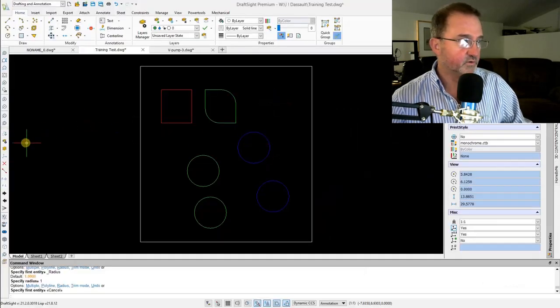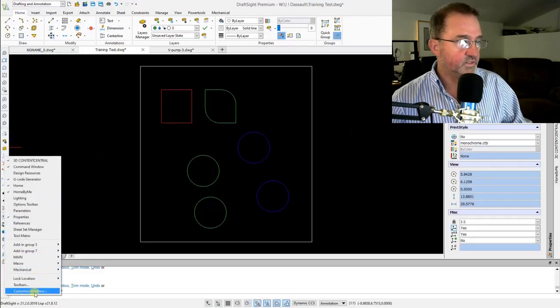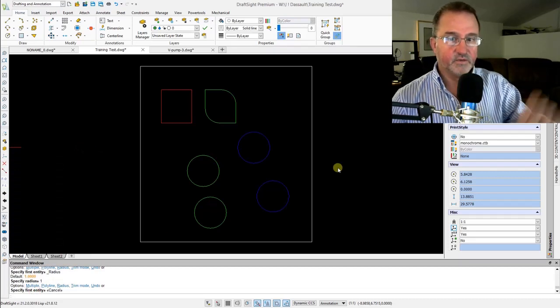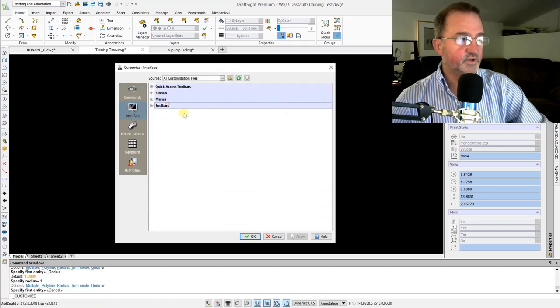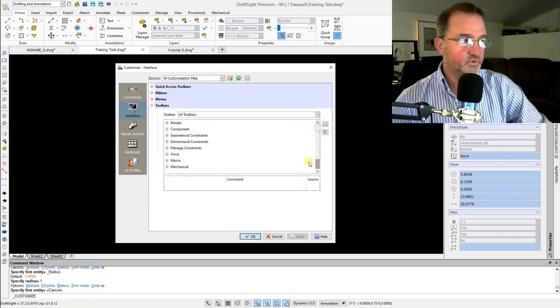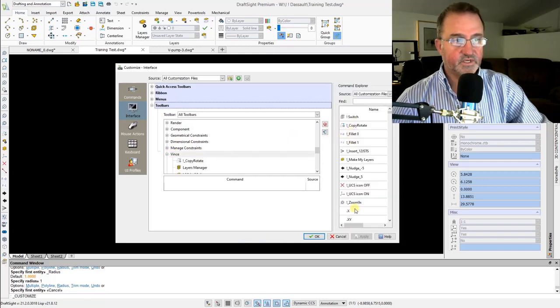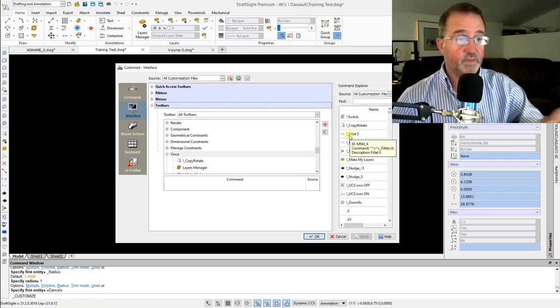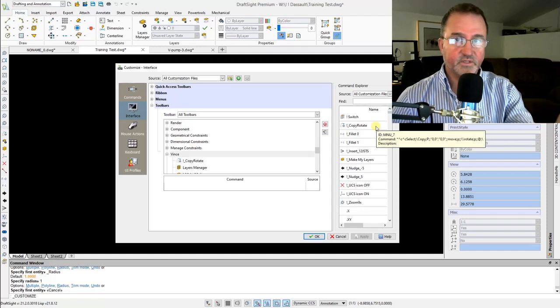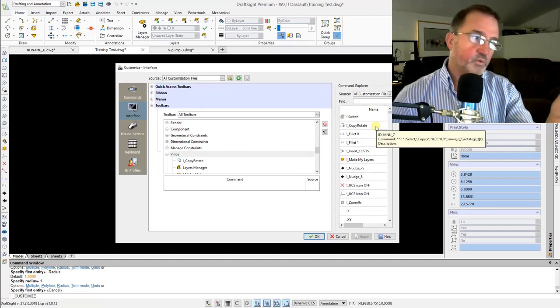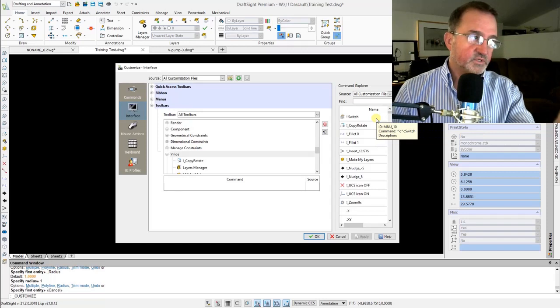so let's just jump back here real quick to show you that once I've created those special custom commands, if I go into my interface and my toolbars, again we'll scroll down to my Vince toolbar here, when I pick on this, you'll see over here are all those custom commands that I created. They will be listed in that list of all the available commands. So once you set them up as commands, you come back down into the interface and you can drag them in.